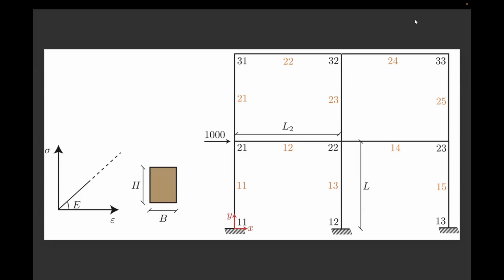Obviously here, and I will show you another trick I used in Python edition, you have to start from 1. You cannot call a node 0, 1, because 0, 1 means 1. So the first digit must always be 1 in this notation. As you can see, when you move here, you have 1, 2, and then you have 2, 1, and so on. I use a similar notation for the beams and the columns.